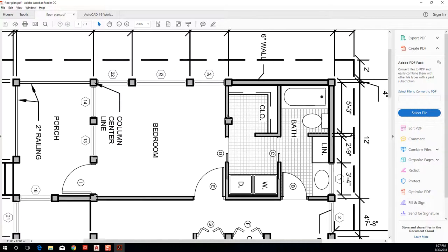So when we read a set of drawings, that's how we're graphically going to read it, right? When you look at this set of drawings, that thick black line immediately indicates structure or important architectural elements. We see a secondary element, right? My eye moves over to here and I think, oh, that's an opening. Number one, the symbol indicates it, but then the pen weight, it's not a thick, heavy line weight like the wall, so I know it's separate from the wall. It's a different category of something, right?